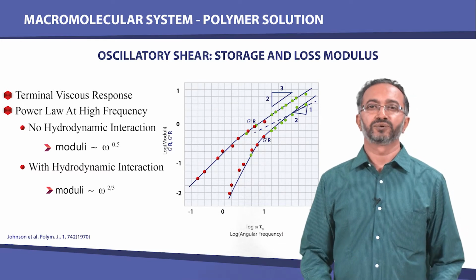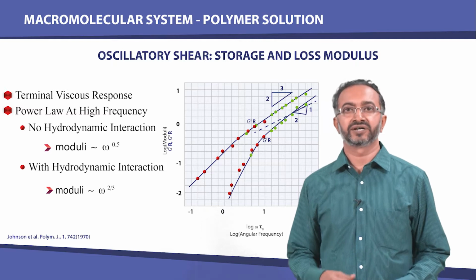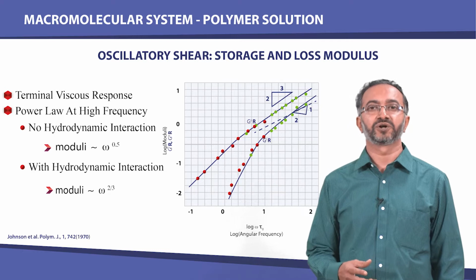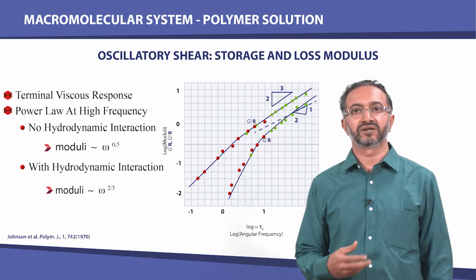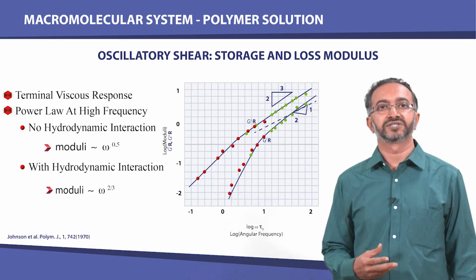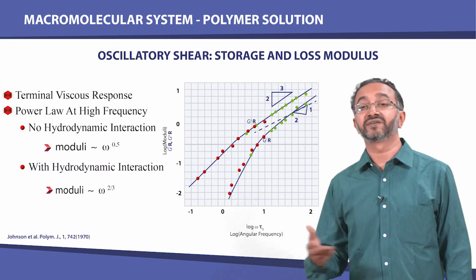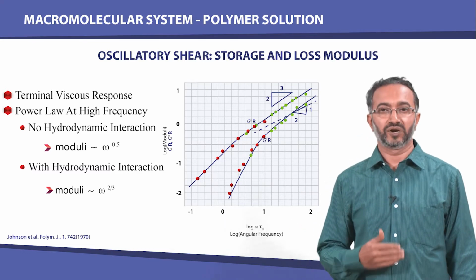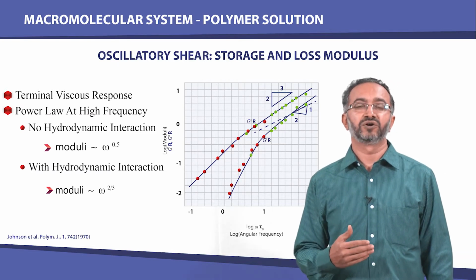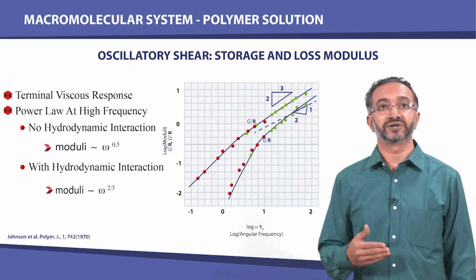we have a polymer solution, and at frequencies of 100 or 1000, in such frequency ranges, the macromolecular subsegmental motions or even the solvent relaxation modes are not going to appear frozen. One will have to go to much higher frequencies for the material to show glassy response, and therefore even at high frequencies we observe that the storage modulus, for example, is an increasing function of frequency.